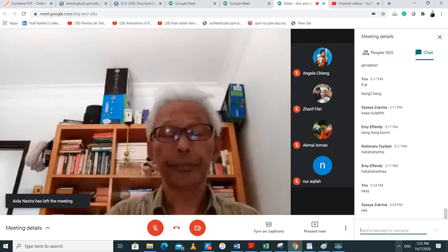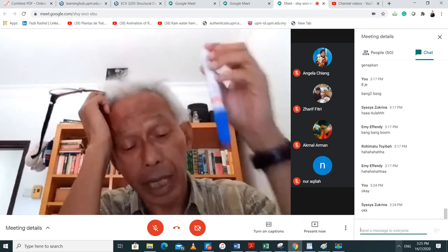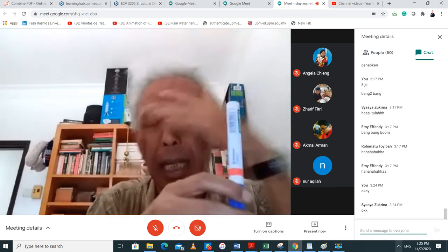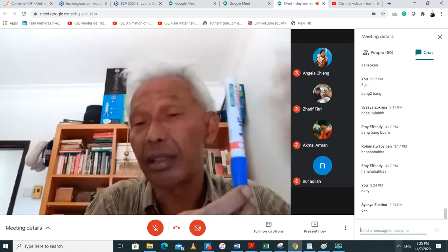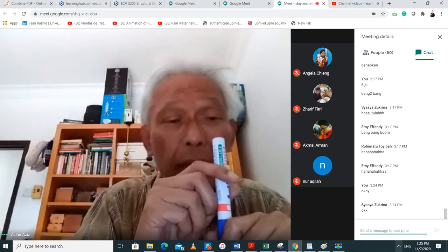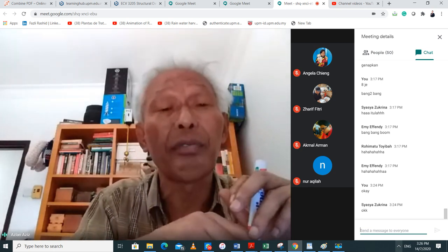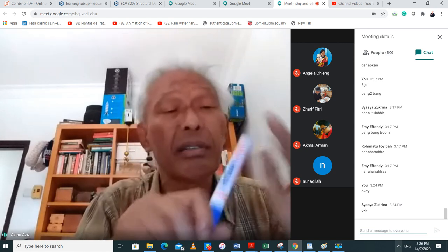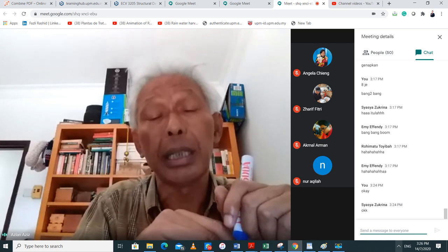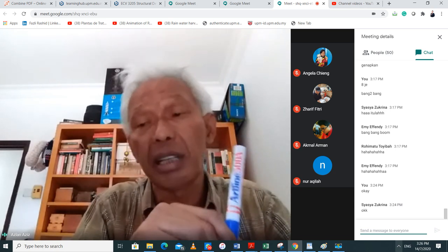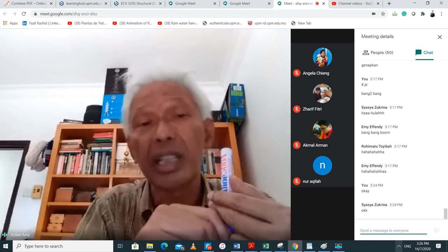Okay. So we started off trying to find the bearing capacity of a single pile. And we said to ourselves whether it is in clay or in sand. If it is in sand, you can use the SPT and CPT. And then in clay, you have all these formulas. So you said to yourself there are three methods by which you would be able to determine the ultimate bearing capacity and therefore the allowable bearing capacity of a pile, whether it is a single pile or in a group.